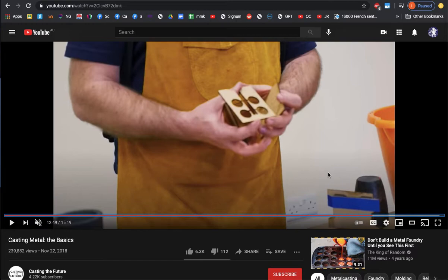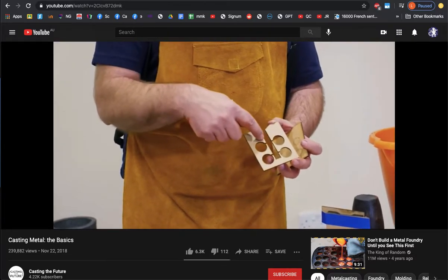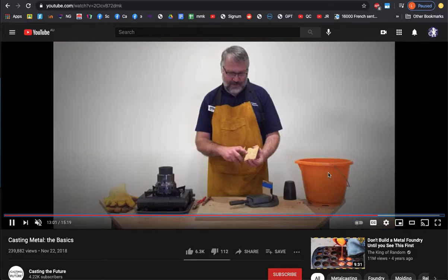Now this die cast, normally we think of die cast as being a metal mold, and usually very, very expensive. But what a die cast mold is just means a permanent mold. A mold that you can reuse over and over again. A sand cast, you have to make the sand mold each time from off the pattern. Yeah. In this case, we can use a metal pattern or a wooden pattern, but a die cast, the idea is that the mold is permanent. And in this case, the mold that he uses is very simple. He's just using a few pieces of, I guess that's MDF or plywood, that he's probably laser cut, and